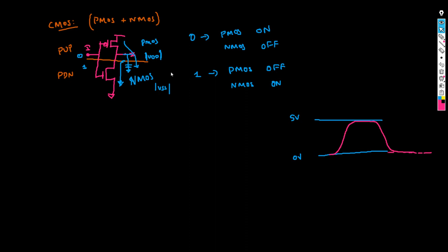Okay, so when you use CMOS, your output waveform goes the full swing, 0 to 5 volt. That is the main requirement in the case of digital chips. As I told you, we operate either in cutoff completely or saturation. In digital chips, we prefer only cutoff and saturation, and analog designers usually prefer the active mode. That is the main thing.